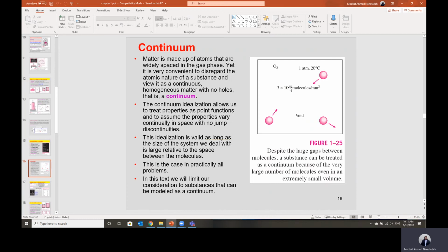And also without any holes or singular point, we should not have a kind of heat source at a given point. If there is a heat source at this point, this is a singular point. Or we may have a vacuum, we have created a vacuum, a low pressure value at a given point. This means we cannot study this point as part of this system. Because to calculate the property of any system like the pressure, temperature, in classical thermodynamics we just consider the average value.